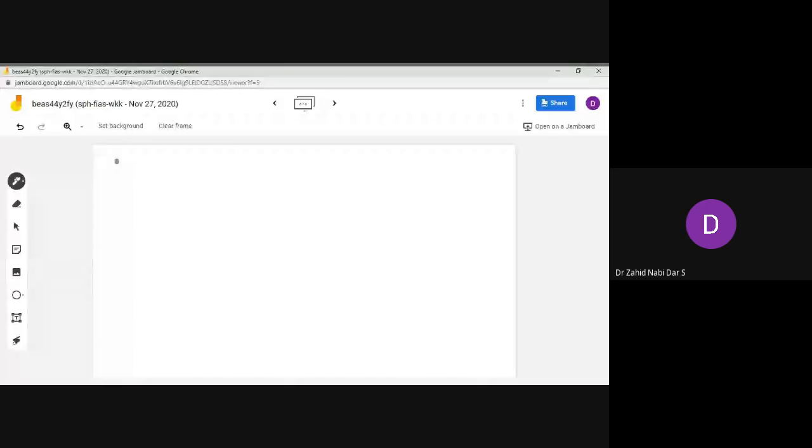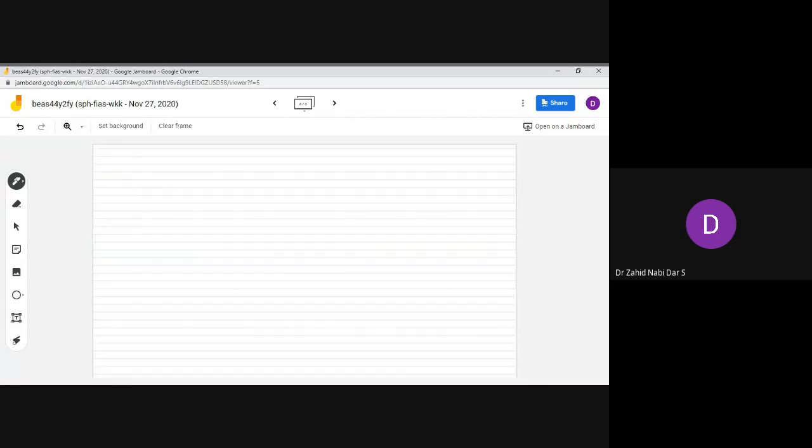So you have to take the total number of stator slots. In order to get that number of slots, you know the value of ZS, but you want to calculate SS. So how will you calculate the SS value? The number of phases is 3, into 4. If you take the Q value equal to 2, in this case you have 24 slots.